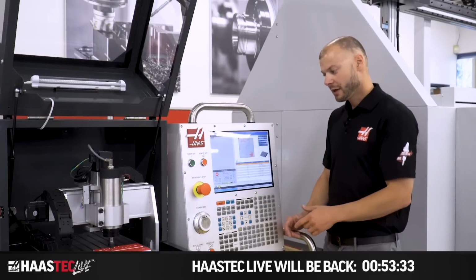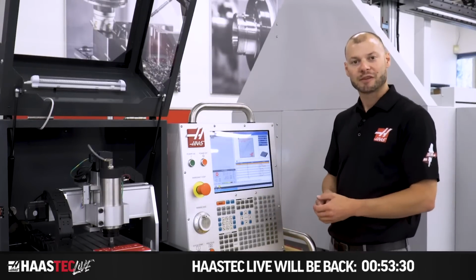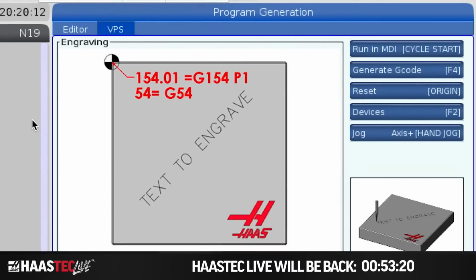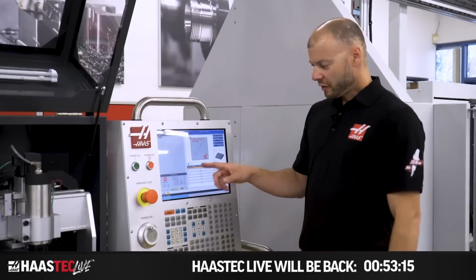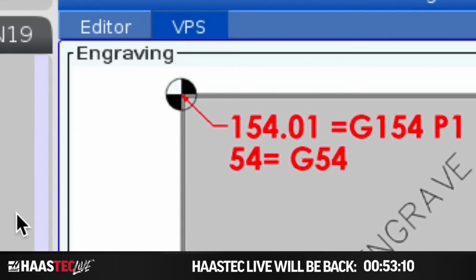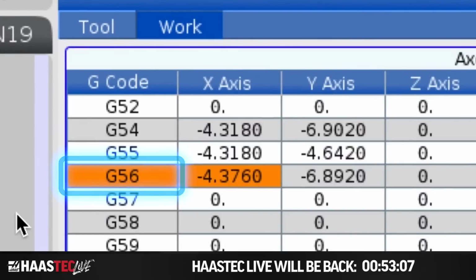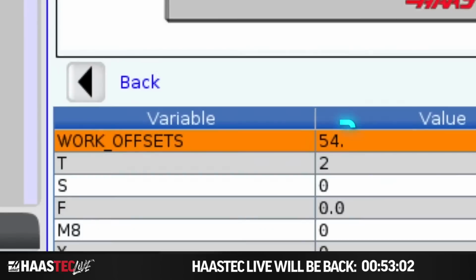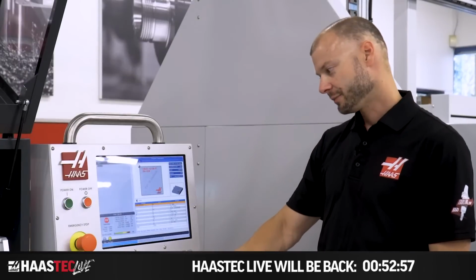So let's see what it takes to operate one of the VPS templates. These are all composed in a very similar manner. And basically, you're just answering questions from top to bottom. We have useful pictures that help determine what inputs we're looking for, and we have some help text down here. So the first thing it's asking for is our work offset. By default it chooses G54, but if you remember, I set G56. So I'm going to enter 56 and enter button, and now we're using offset G56.